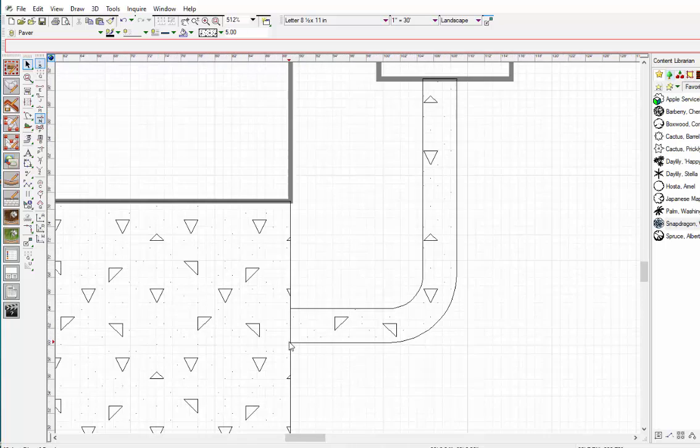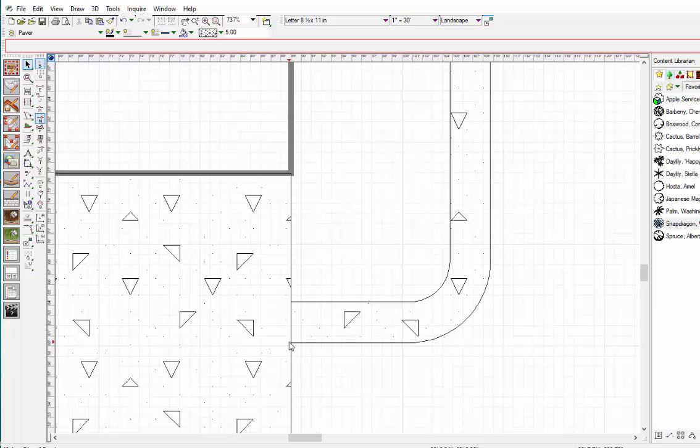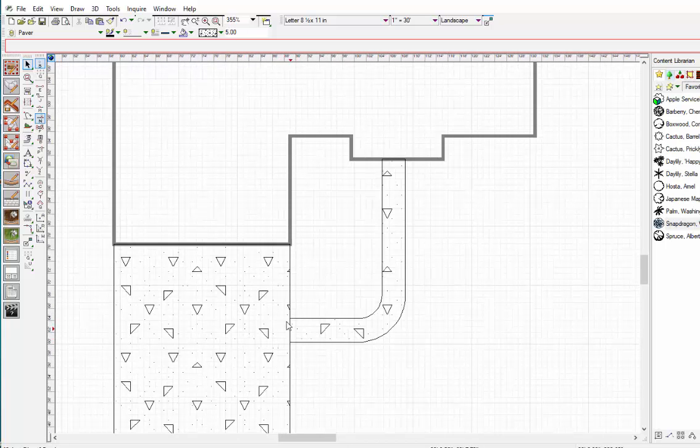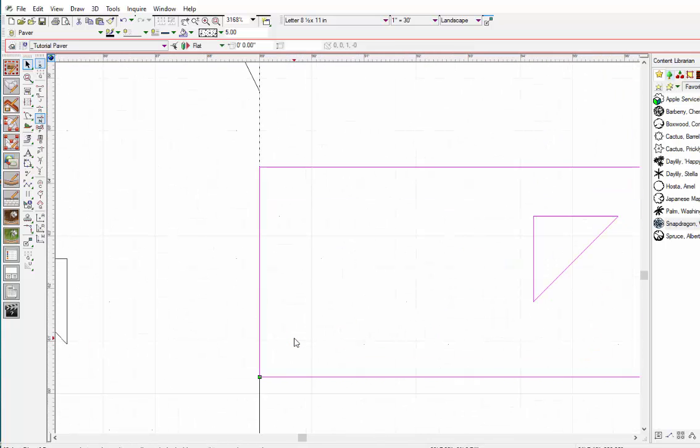All right, now some other thing that we can do here is we can merge these two shapes into one. So I have a driveway and I have a sidewalk. Now this technique does require that the lines are matching up. So again, I had used the snap tool to snap directly to here, so I don't have a gap here.